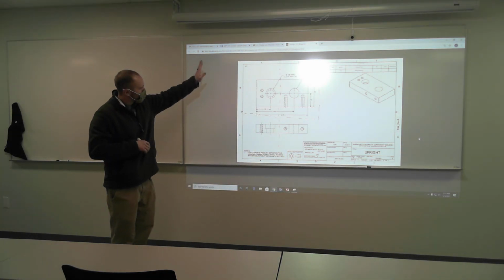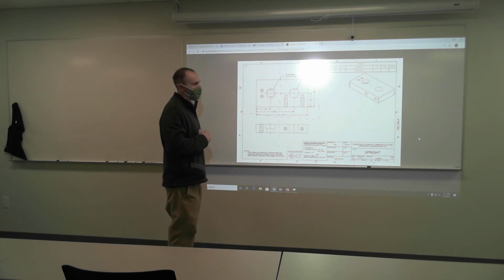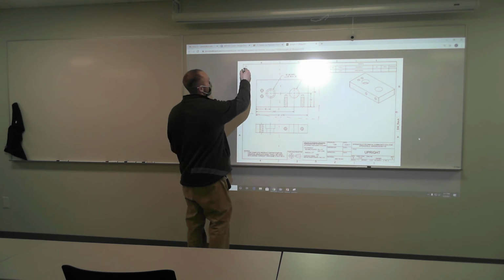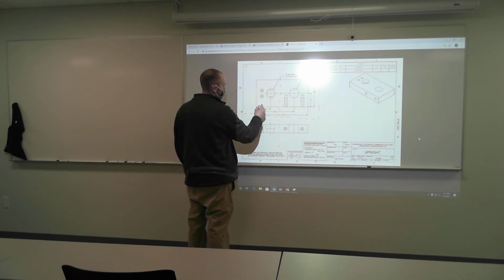So basically, I'm going to start systematically, go top to bottom, left to right, just like you would if you're reading something. And if I hit a dimension, I'm going to put a number on it. So boom, that's the first one I hit. I'll put a number 1 and I'll circle it.